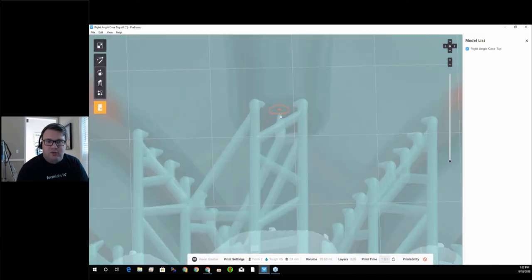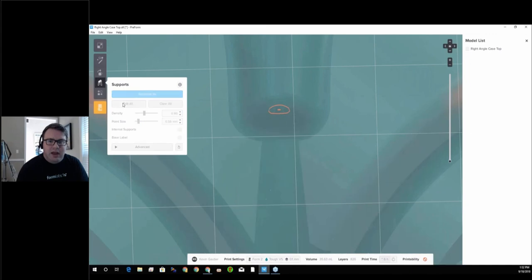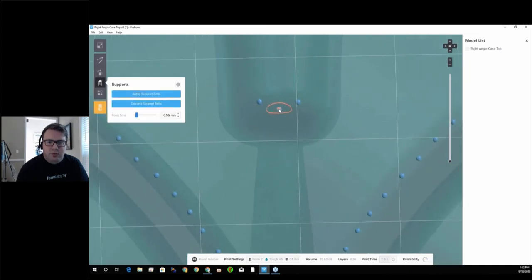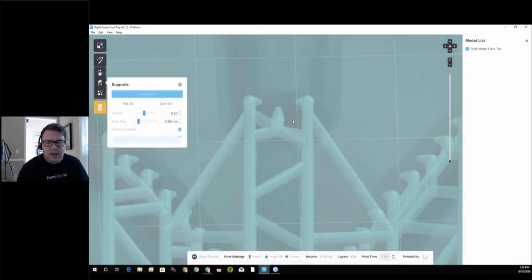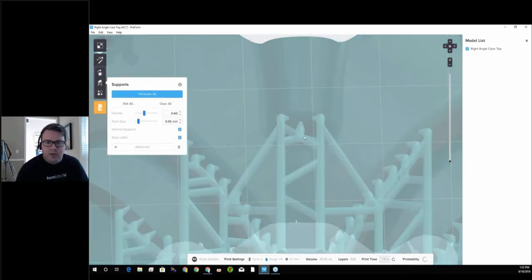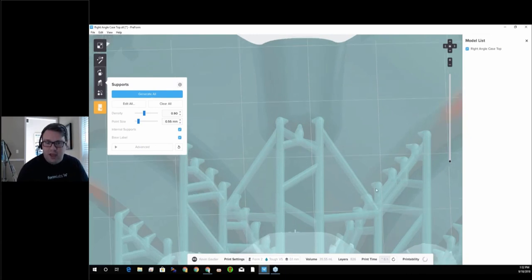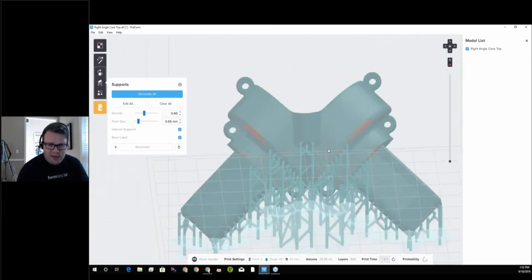What happened was I just put this lower support slightly too low. So we can go back to the support tab, edit, and then just move this support over to here and apply that edit. That'll clear up that unsupported minima. That's just one of the consequences of doing a live software demonstration. But either way, that should totally fix that.